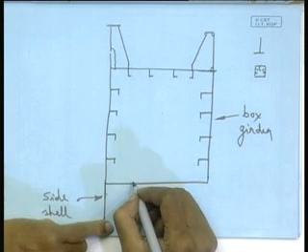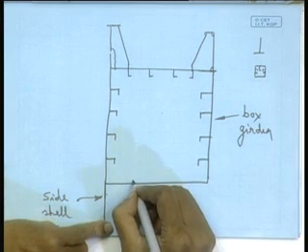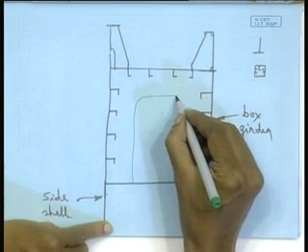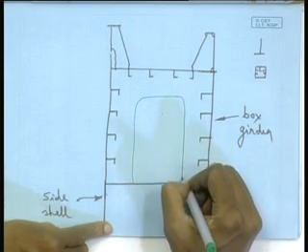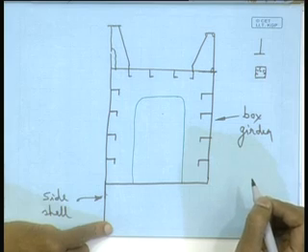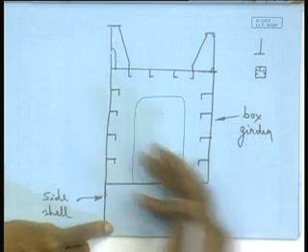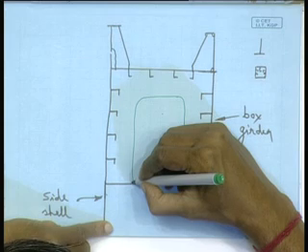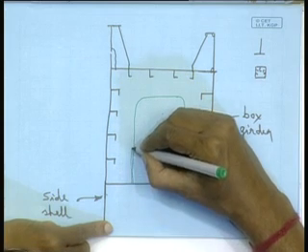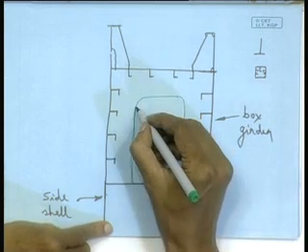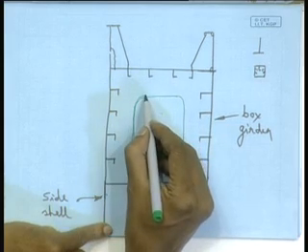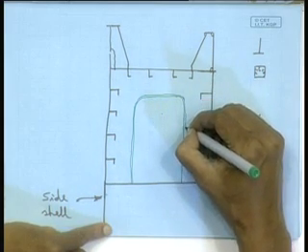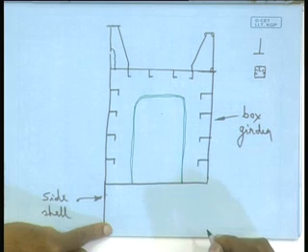So, together it can be one plate which can have, like in bulk carrier we had the transverse in the top wing tank, same thing, this is a transverse having a flange. This is drawing a double line, means I am showing that at the edge there is a flat bar welded, which functions like a face plate.